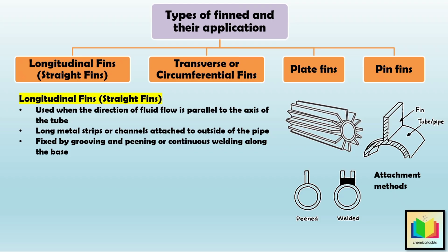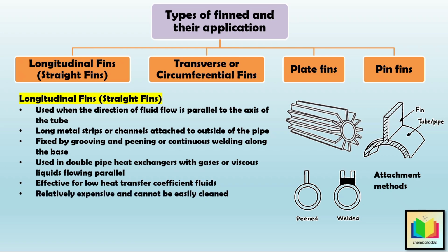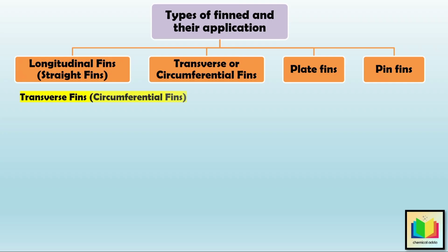Then, longitudinal fins are commonly used in double pipe heat exchangers, especially where gases or viscous liquids are flowing parallel to the tube axis. They are very effective when the fluid has a low heat transfer coefficient. But there is one drawback: they are relatively expensive and cannot be easily cleaned. So, they are generally used only for clean fluids, or in cases where any dirt that forms can be boiled out. Now, let's look at transverse fins.